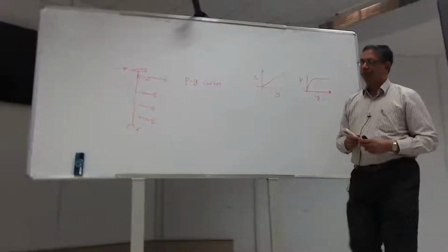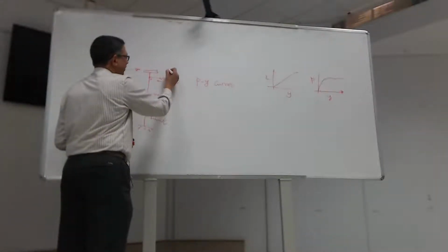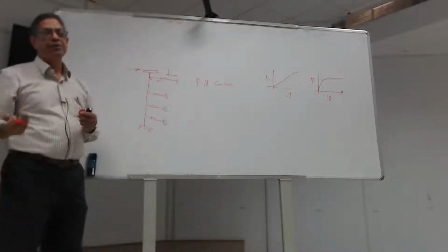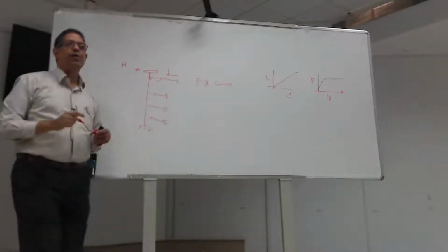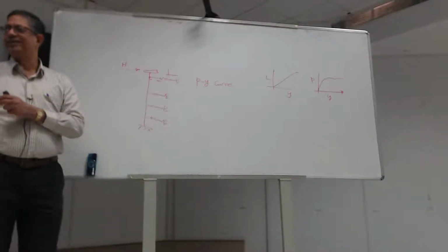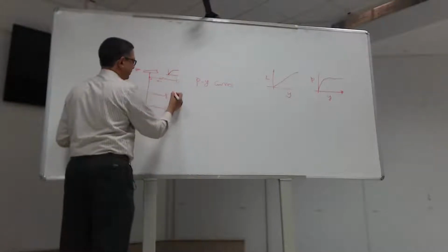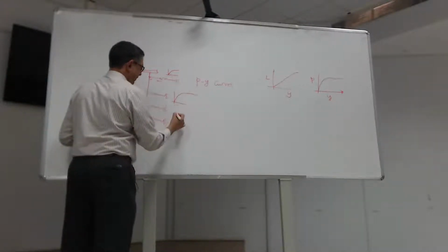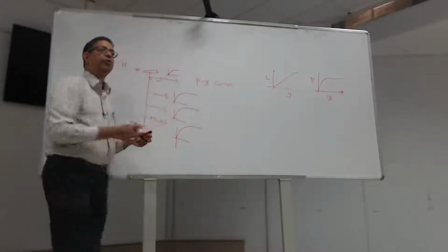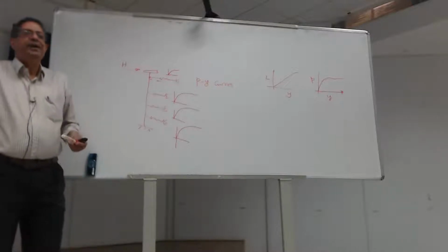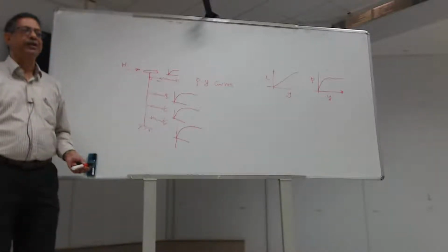Now, one of the nice things with this P-Y analysis is that I can choose different springs. So these are now nonlinear springs. So the stiffness depends on the deflection, which means you cannot solve this for any horizontal load you're applying. You cannot solve in one go. It's not a forward translating solution. You choose even higher like that. So as you go deeper, you can choose the same family of curves, but you proportionally increase their size, which makes sense because you can select the stiffness characteristics of individual springs the way you want. It's just a matter of coding it.